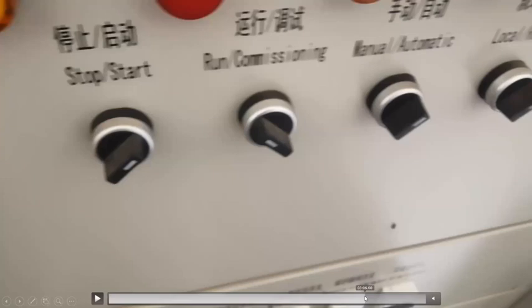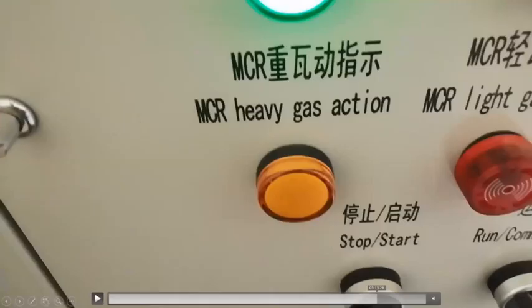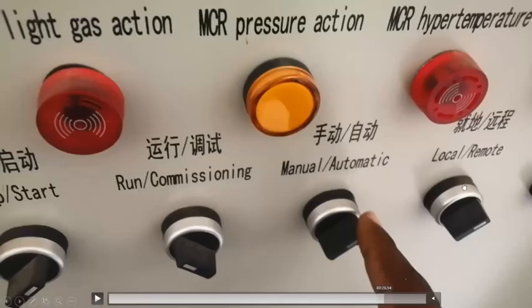Also, we have a button here indicating whether it's running, start, or off. At this point, it was running. Also, we have this button, which you can change to local or remote. By local we mean manual. You can change it to manual, then you can operate these buttons. But at this moment, it's connected to remote, such that you can control it using the computer.